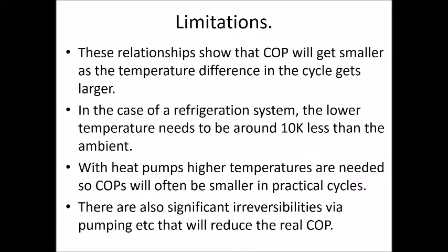And what it means is that the COPs really start to plummet, and you start to get really poor COP. And in a lot of cases, and this is why heat pumps can be a little bit controversial, the COP creeps below 1, which is telling you that for the amount of work energy you're putting into it, you're getting slightly less heat energy back. So from the perspective of paying my electricity bills, I may as well have just used the electricity in the normal way of passing it through a coil to heat up a heating coil, just as I would have done with an electrically fired heater.